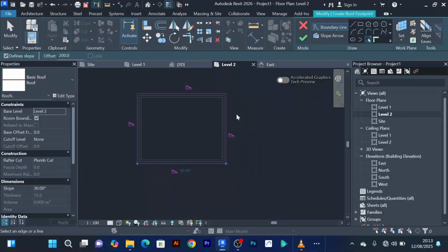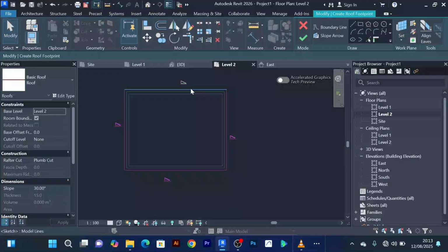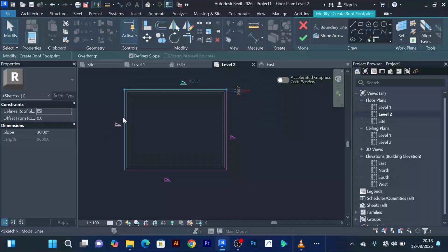So we shall just now click on the exterior sides of the wall, and the roof we have created should be within here. So after clicking on the drop down, you can look for the roof you have created. I'll just select it, and one thing we can do here is to control these slope angles. Now you realize currently the slope angles are 30 degrees, which I believe is a lot. So let me just put here, let's say 16 degrees all round. Here also 16 degrees.